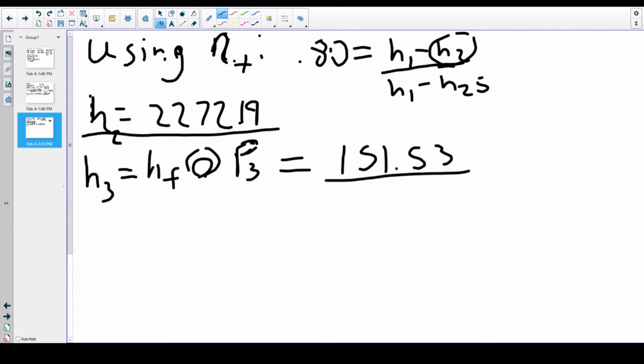So for the next part, we move on to solving for the enthalpy after the pump. Basically what I'm writing here is just that S3 equals S4S. We are assuming 100% efficiency, just like we did with the turbine, to try and locate an H4S value.